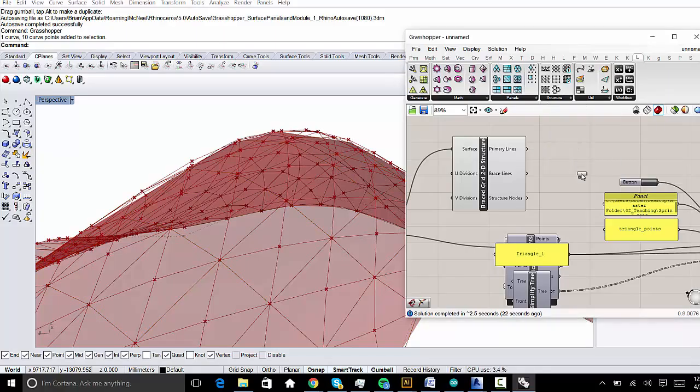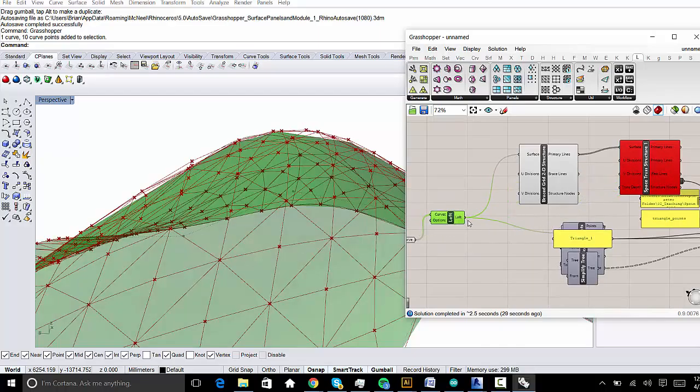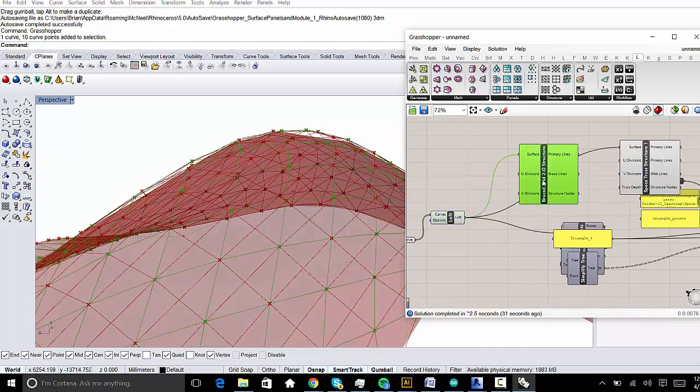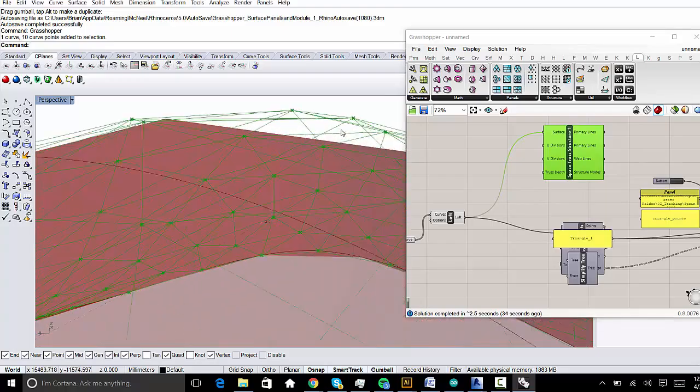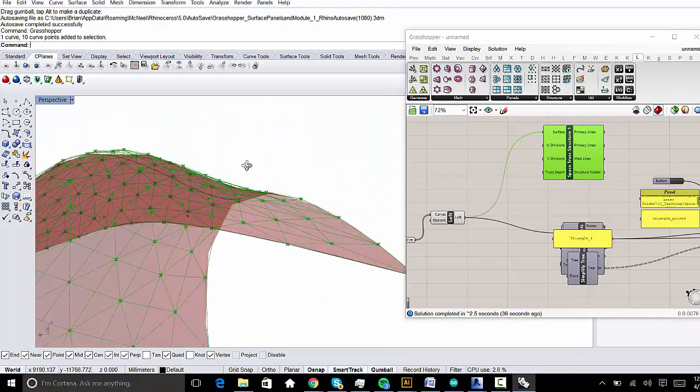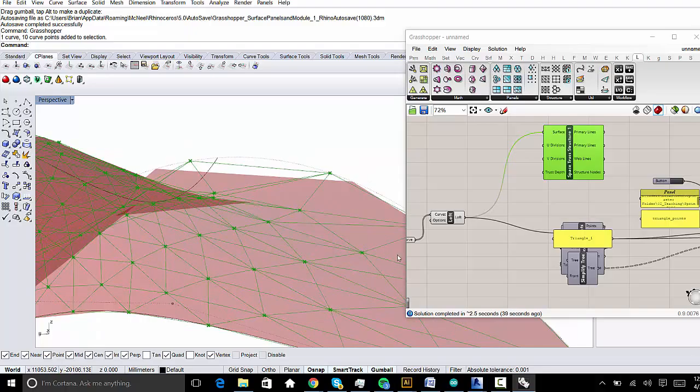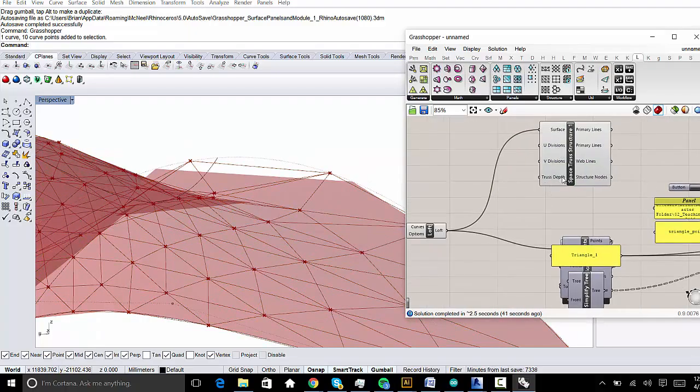Other useful ones, space truss. These are the really cool ones because they usually, I'm sorry, I shouldn't feed my surface in there, not those lines. Delete that. And you can see that this structure actually doesn't have much depth because it's so big. So I'm going to change my truss depth. It says it's 5. I'm going to make a slider. 5 is the lower end, 10 as the default, and 30 as the large or the maximum of the range. Put that in there.